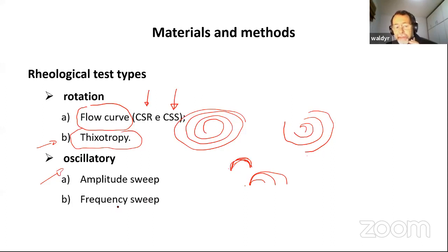Or you can maybe do it a different way. You keep the amplitude, but change the frequency. And then you have this frequency sweep. These tests are very important to discuss the gel-sol behavior. If you remember the chemistry, gel behavior is when the material behaves more like a solid, and sol more like a liquid.